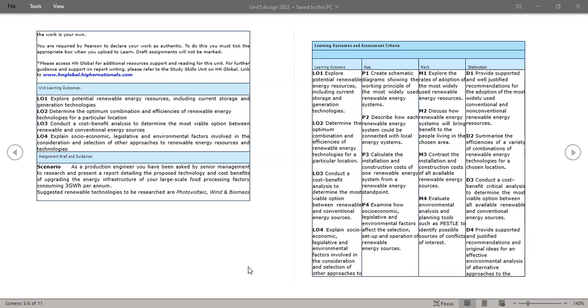You can work out rated power by looking at case studies, and you can look at the claimed energy output per annum, and you can work out load factor from this. Both size and efficiency affect power output and, obviously, energy out of a system. Load factor affects energy out, not the rated power, because it's the amount of time you can run the rated power for. You can do various comparisons.